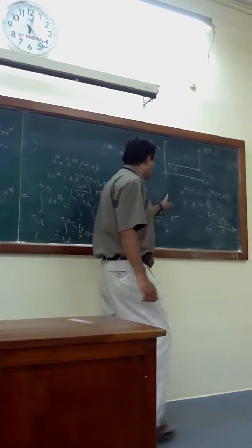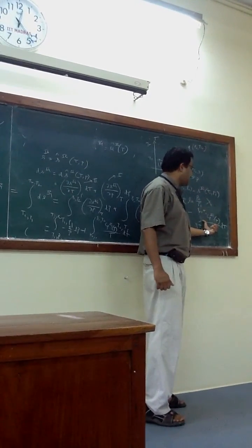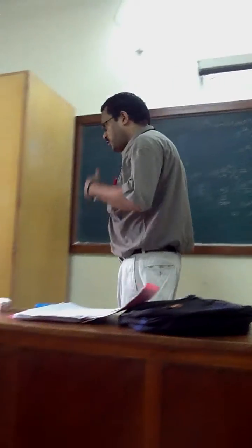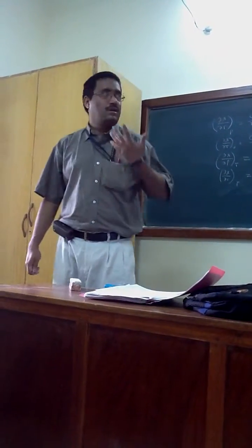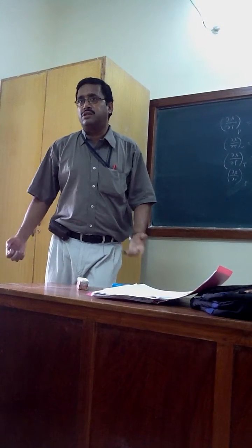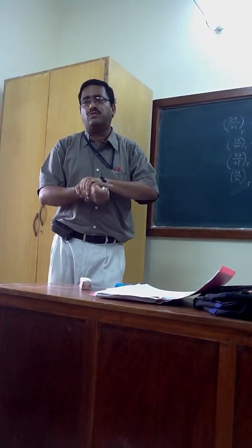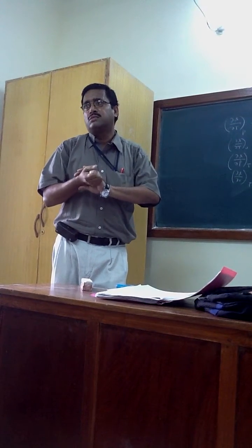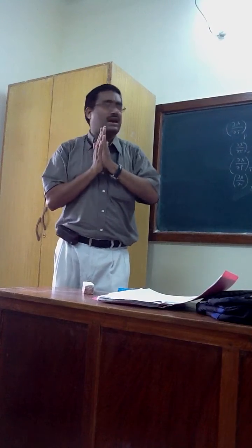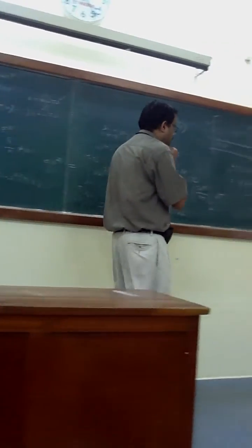So if you want to do delta S in the T-P plane like this, it will be completely unknown. But we have to calculate delta S, and the pressure is not always tending to zero. Pressure will have some finite value. The material is real, not ideal. If it is ideal, it's okay. If it is real, this method will not work.